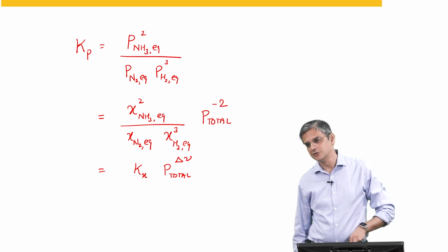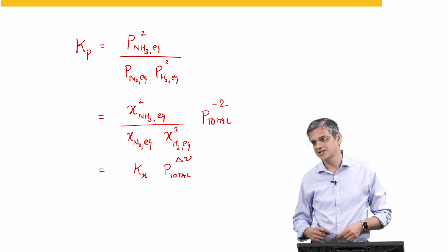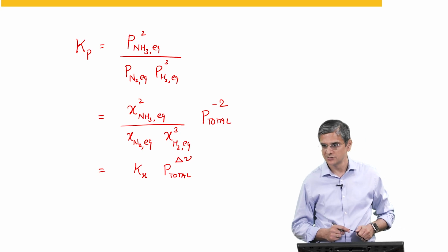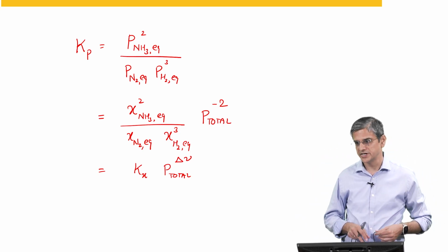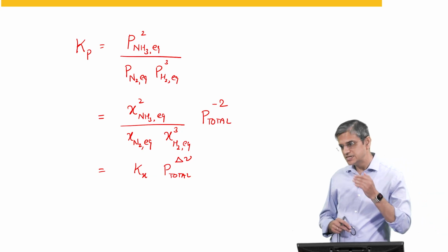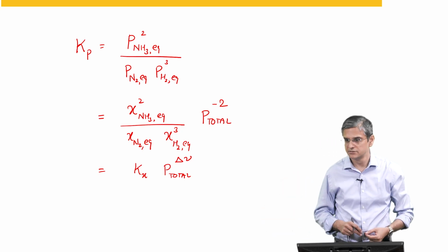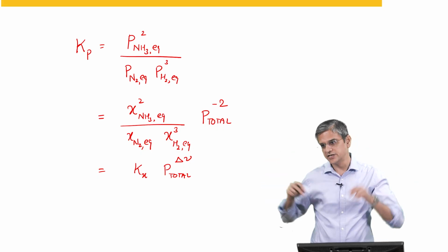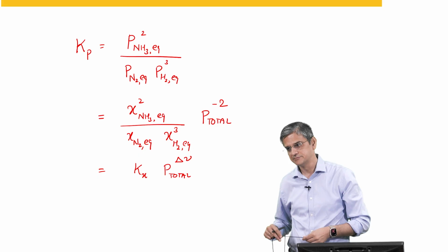To expand the answer to your question, there is no restriction about constant pressure, constant volume and so on. This is mathematically equivalent with no assumptions being made. Equilibrium is at the conditions in which equilibrium is calculated, which for a well mixed reactor will be outlet conditions, or for a batch reactor will be end conditions.